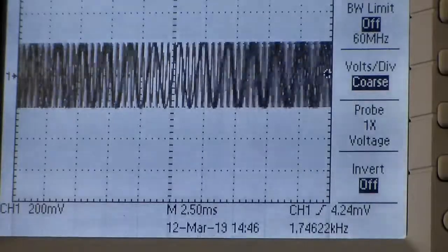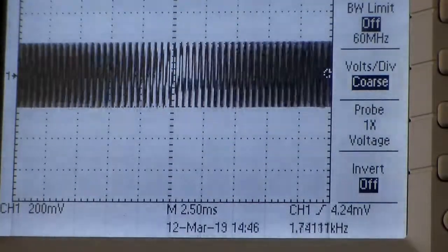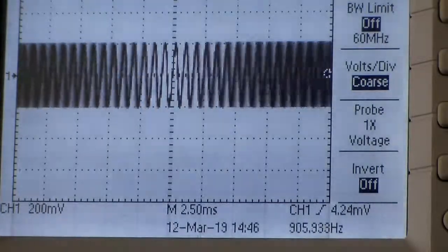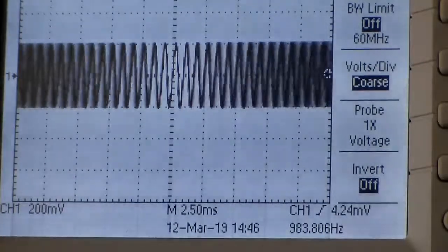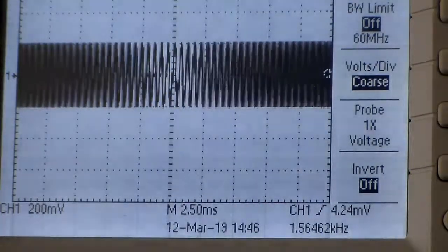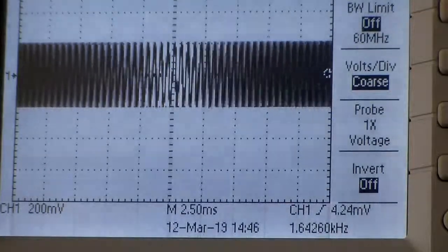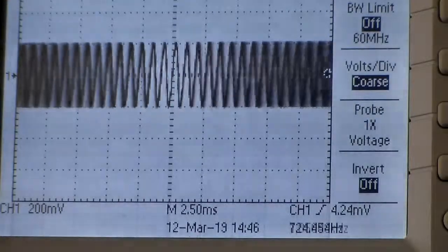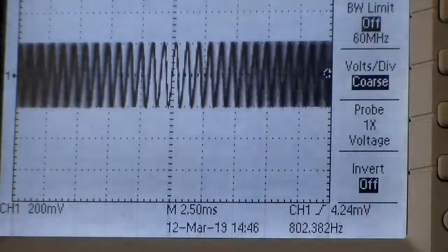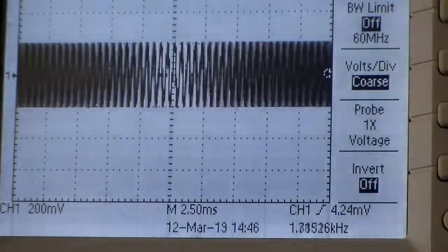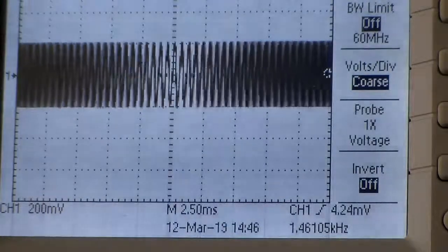Again, this stuff is really cool, and it could be used for a number of circuits. One in particular that we can use this for is, let's say we created a filtering circuit, whether it be low pass, high pass, band pass, or stop band, and we can actually check to see, as we're sweeping our frequency, how the filter actually works, to see if, for instance, as it gets to a certain cutoff frequency, it's at half power or whatever.